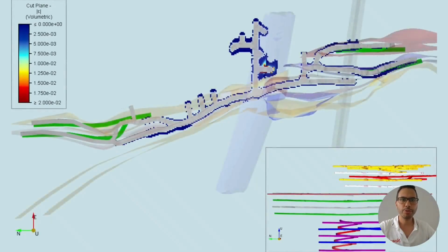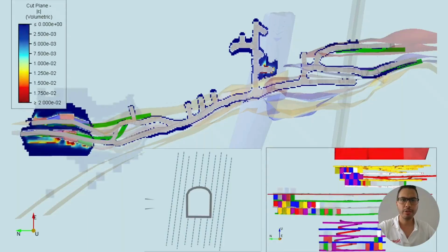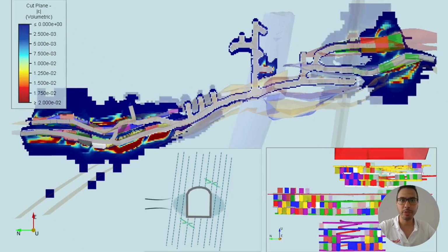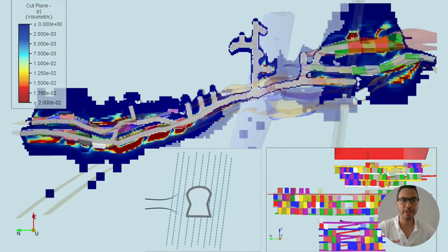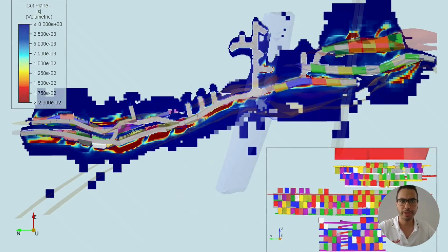Here I just want to show you the risk at one particular level by looking at the evolution of volumetric strain with the mining sequence. Note that this model assumes subvertical joints, therefore most of the strain will be in the walls of the development rather than in the back, because in the back normal stresses on the joints help with the shear strength.